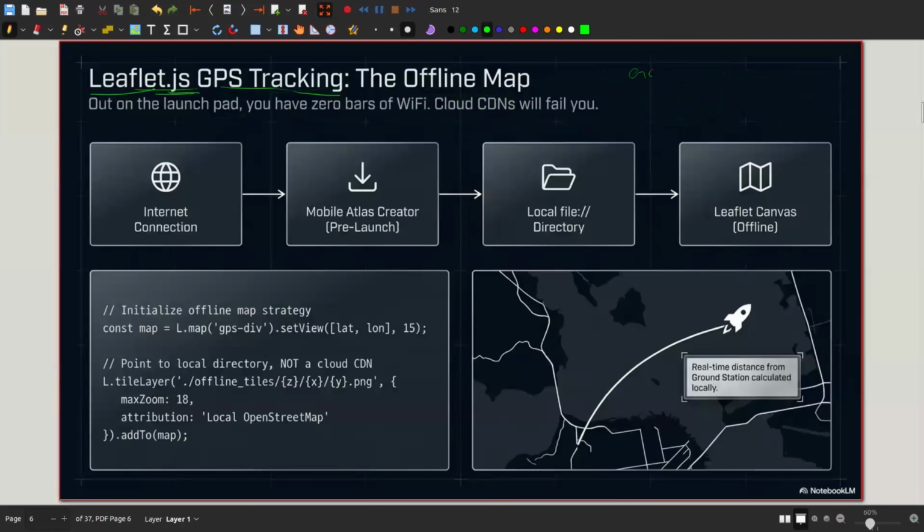So in building GCS, we have to realize that we are not necessarily going to have components like leaflet.js. Even if I said that we are going to use this, in most cases, the area where the rocket is going to launch, you won't find any network services. You can simulate the sensor readings as well, by creating a Python server and then a script to catch the values from that server. So you can use the Python library as a backend and a front end interface for the backend.